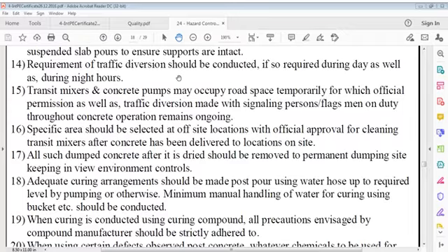We can stand there because your station pump is stationed, and maybe sometimes 50, 60 transit mixers come to site the whole day. That causes a road jam at your entry, and sometimes there's a long queue of transit mixers on your street that can obstruct the flow of local traffic. So there should be someone to guide them how to come out of that jam, and there should be a location for these transit mixers to stand safe on the side of the road or inside your area.